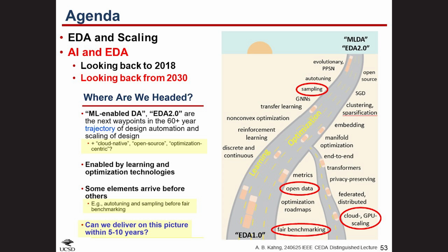The figures at the top show the post-routing results, and you can clearly see the data flow reflected in the DG-RePlAce result, which is at the right. And the table shows post-route opt metrics, again from Innovus 21.1, again a hybrid open to closed tool flow.